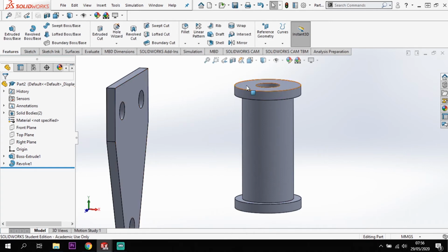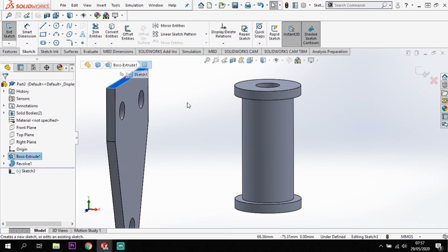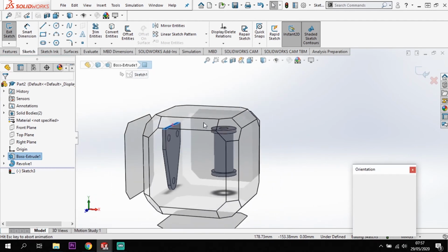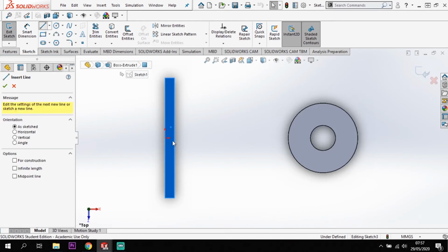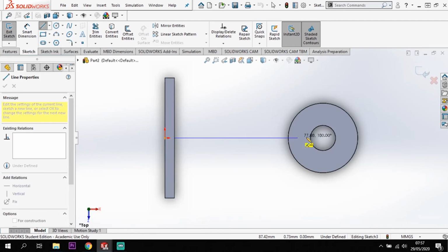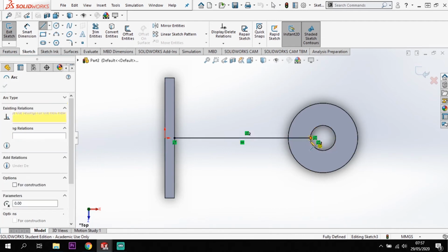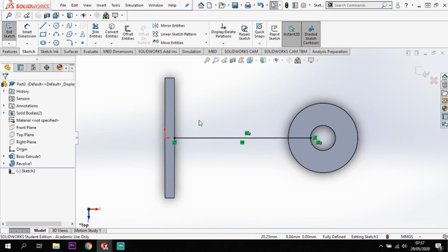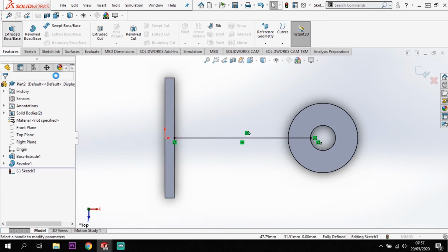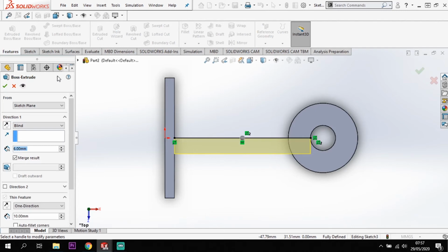So what we're going to do next is just connect them up. So through the top surface here, so just click on the top of that. I'm going to sketch. I'm going to move my view so I'm looking at it straight down, and I'm just going to draw a line, and that line is going to come from this front face across to this face here where my hole is. Okay, so it's just a singular line. Now from that one line, I'm going to Features and I'm going to Extrude. So this is going to be extruding using the fin feature.